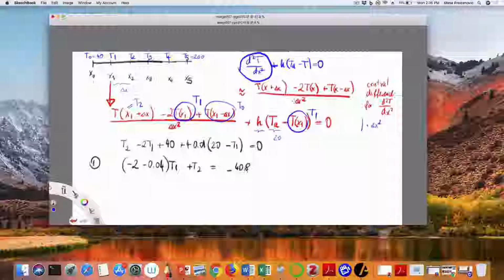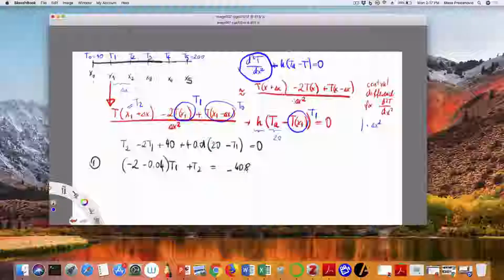So what this really says is that I would have certain dissipation of my temperature, but this contact between two different materials kind of involves a step function because they have different thermal capacities. Okay? So whatever the metal can deliver, air cannot necessarily receive at the same rate, which causes a step difference in the temperatures, so they don't equilibrate instantaneously. But I am losing some heat to that, and the rate of that loss is governed by H. So I am losing some heat to the environment.